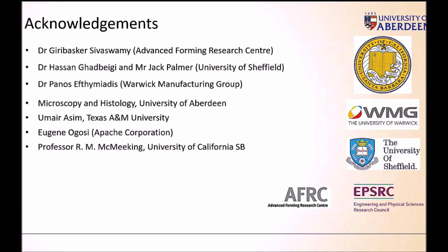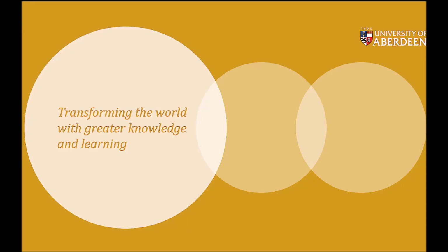These are just some of the acknowledgements of the collaborators we have worked with from the perspective of advanced manufacturing. That's what I wanted to summarize in this quick time. I hope you find it useful and that it was not too complex. The idea is we have crystal plasticity based models, which are generally user material subroutines, UMAT, interfaced with Abaqus finite element software. So we can model single phase and dual phase alloys, whether they are FCC, BCC, or HCP crystal structure.